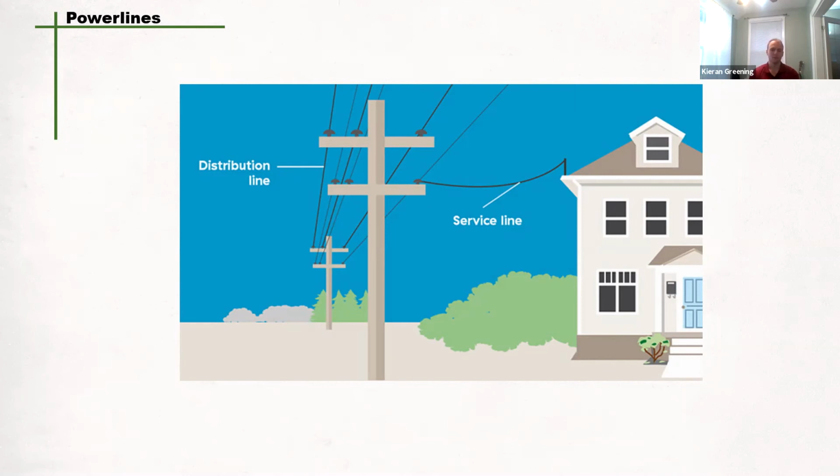And as well for below ground, in Saskatchewan, getting line locations to dig is a regulation. If an underground line of any sort is contacted, energy can be released and cause serious injury. Not only that, but that's an OH&S reportable incident that they will expect you to report on. So I'll just quickly read from the legislation that says this.